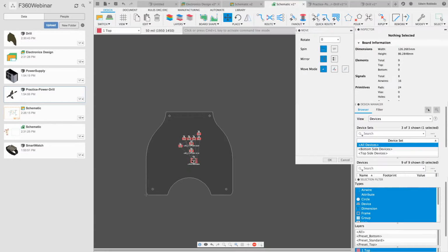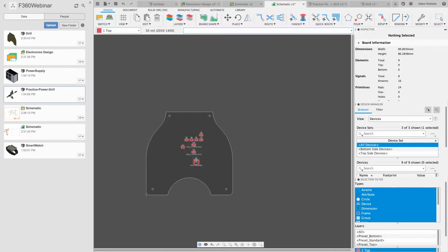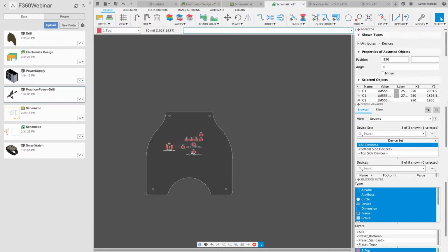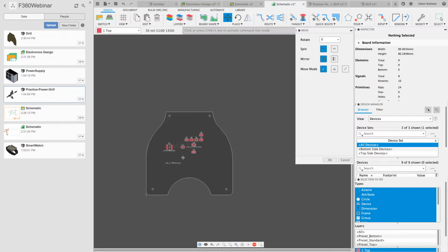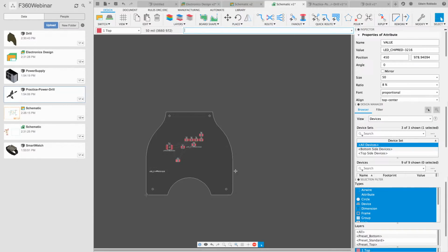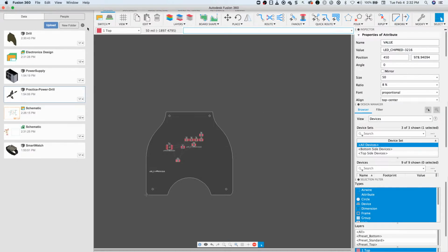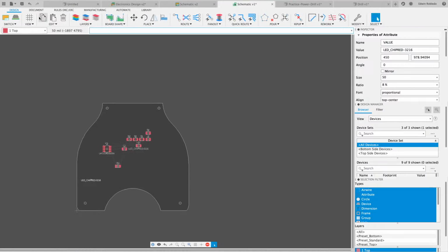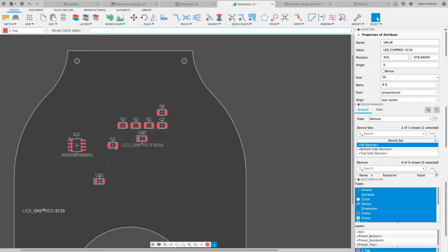In this case, I'll bring them in all as one unit, and then once I have them here, I'll start moving them around one by one. For time's sake, I'm not being very careful with my placement, because I'm trying to do this as fast as possible. Your zooming tools are on the bottom of the screen, as you can see right here. The interface is extremely similar to the one in the schematic editor. Let me accommodate these parts so that we could do some manual routing.